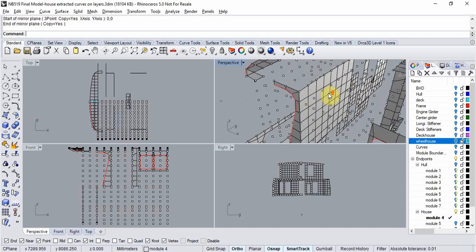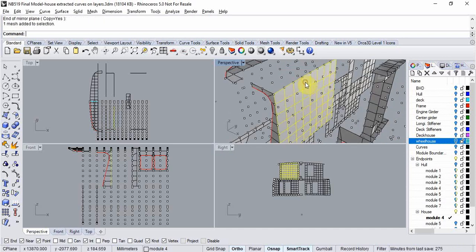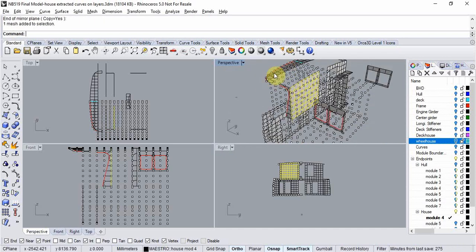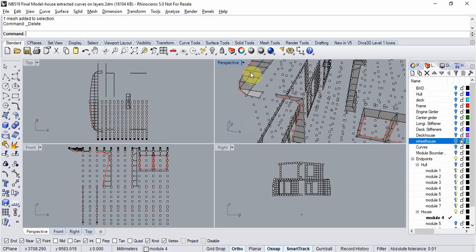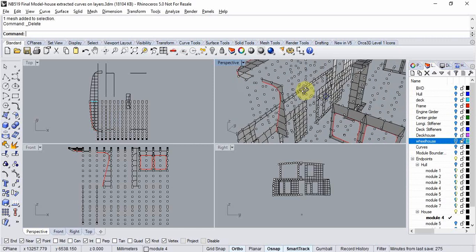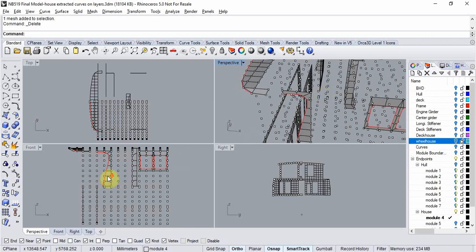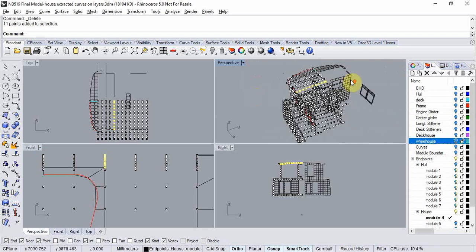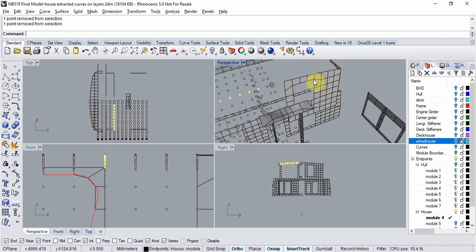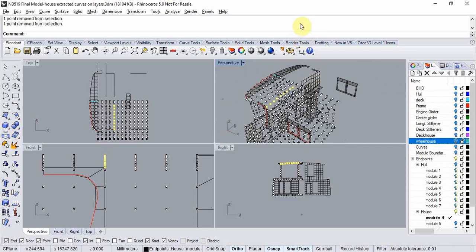One last thing to review is how we created these bulkheads. Similar to how the overhang was created, we lofted a surface and converted it using the mesh from the NURBS control polygon. But unlike the original overhang mesh, we had separate lines when we created the lofted surface. Here, we would simply create the polyline for the top of the surface,